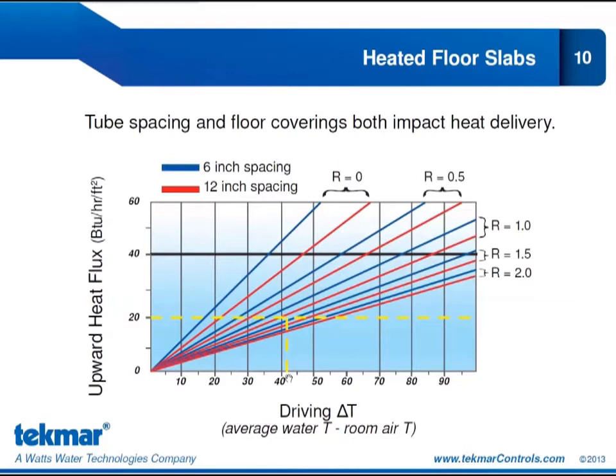However, we have definitely sacrificed the efficiency of our heat pump. Once our entering load water temperature is climbing from, let's say, 95 to 125, that ends up being quite a big jump in heat pump efficiency.